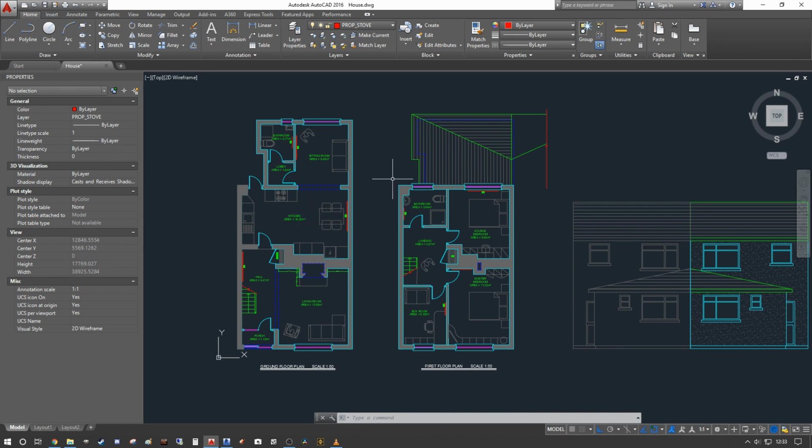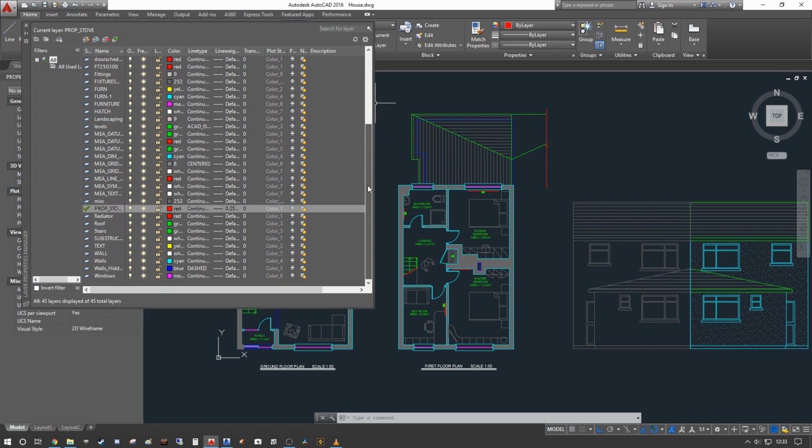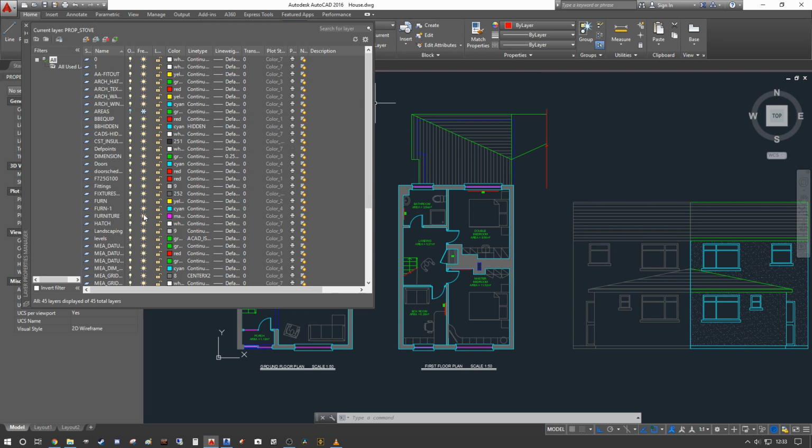The next thing you want to do is essentially go through your layer properties and freeze anything that you know is excessive or superfluous for what you're actually taking across. So for example, I could probably go in here and freeze these guys here, layer 1 and layer 2. And I've also frozen off the areas. I also do not want to show the text elements from the CAD file within the Revit environment itself. So we'll go down and turn off the various text layers here. I'm going to freeze all of these essentially.